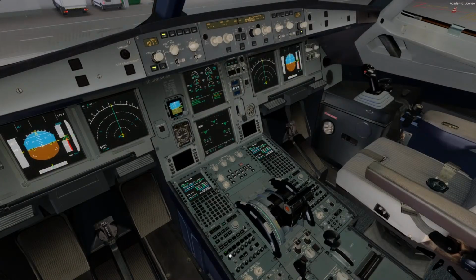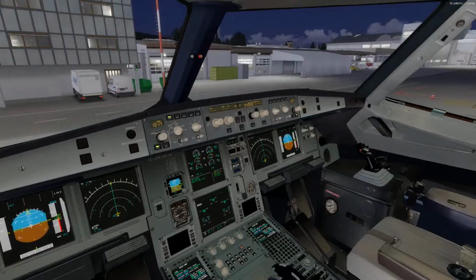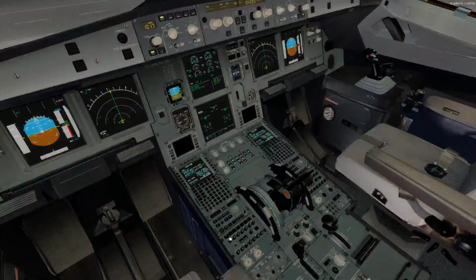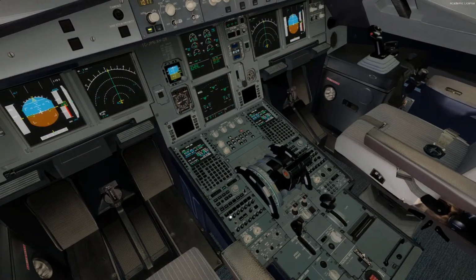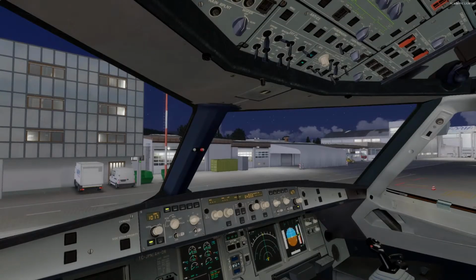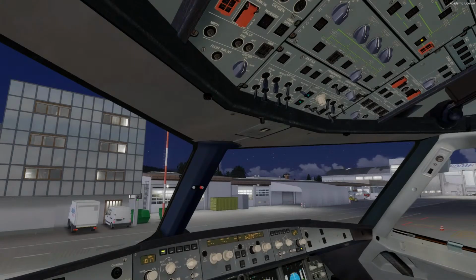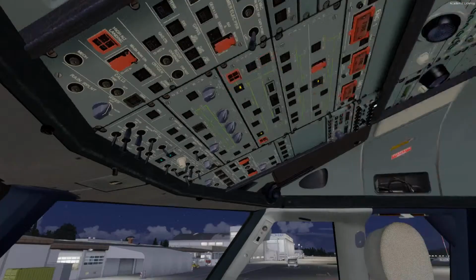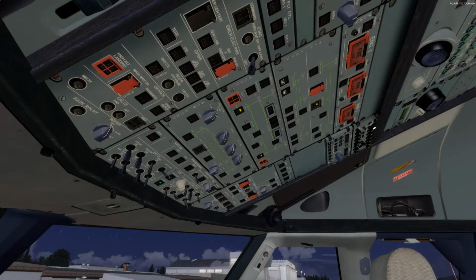Now I'll go to Unicom back again to 122.8, and the APU is on and running, and we'll now shut off engine number 2 and engine number 1. And so we have finished our flight. The beacon light can now come to off, and the seatbelt signs will be set to off. The fuel pumps will be set to off, and I will turn off the packs.